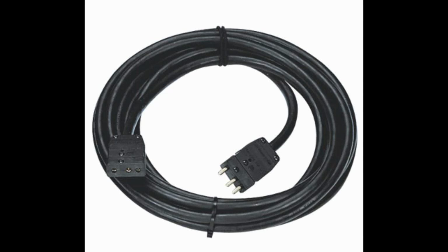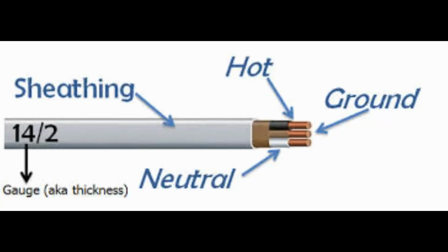Cables are how electricity is carried from the source to the instruments. Flexible extension cables are used to connect instruments that are not near a power connector. A cable should consist of 3 cores or small cables bound together in a protective sheath. Each wire in the cable is color-coded and performs a different function. These colors should inform you as to which wire should be connected to which terminal of the plug or appliance.